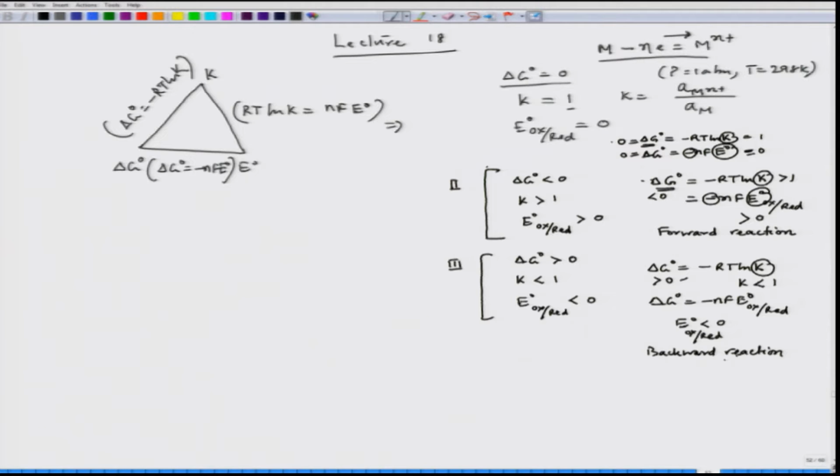When we say that metal ion would get reduced, it means that the corrosion process, that ion formation process, would not be probable; rather, deposition becomes probable. In that case we might say that corrosion is controlled or minimized, but in the other case corrosion is maximized. And in this case it is equilibrium, so the corrosion as well as metal deposition are happening at the same rate. So these three situations, this is situation 1, this is situation 2 and this is situation 3.